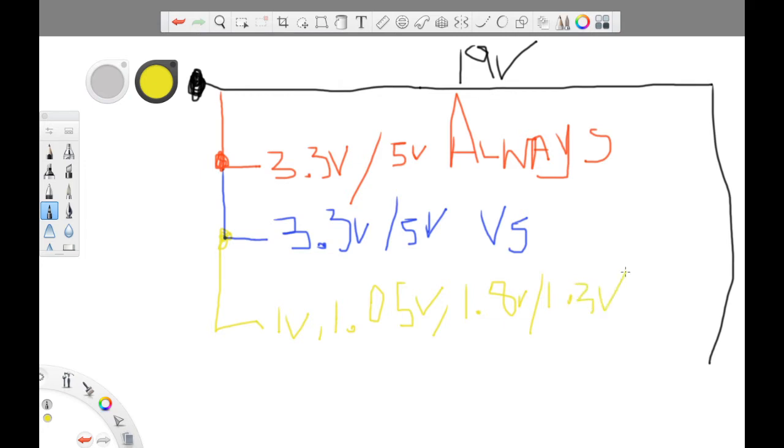You will have all those kinds of different voltages. Okay, these ones are for the CPU, for the PCH, for the graphics card, for north bridge, south bridge. Okay, all these kinds of voltages will come after you have the above voltages.